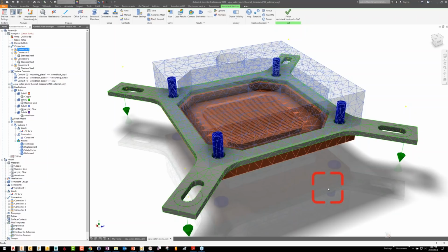If I'd have built this entire model as complex as I want to get it, and then hit go and have it fail, well, now I have to sort through all kinds of stuff to figure out where my failure was. By running it again, as soon as I switched those contacts, I knew what the problem was, because it was the last bit of complexity that I added. I knew right where to go and who was causing trouble.